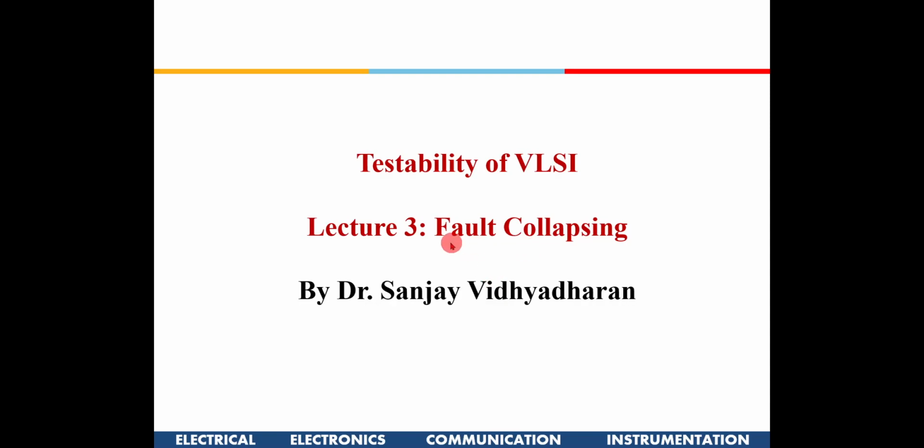In the last class, we learnt about the various kinds of faults which can occur in a VLSI chip. Essentially, during fabrication, there will be defects. Those defects could be a cut in the wire connection, or an unnecessary connection between two wires. Or there could be a transistor which is not fabricated properly, so VTH may be way too high, or way too low. Those are the defects, but it is difficult to model all of them.